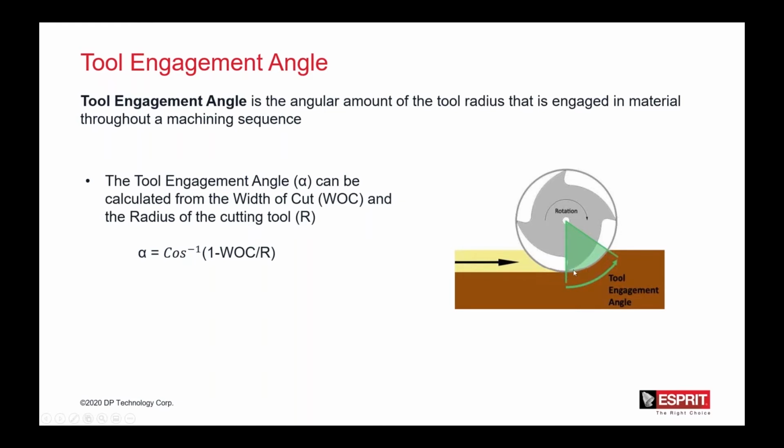We're going to try to define a constant tool engagement angle, and we're going to typically define this as a lighter engagement angle. It depends on your material type. I know with some steels, you typically define like a 25 to 35% engagement angle. And this is where you're really allowing your advantage of increasing the feed rate and the total depth of cut. Because we're defining a light tool engagement angle, you're reducing those forces on the tool itself.